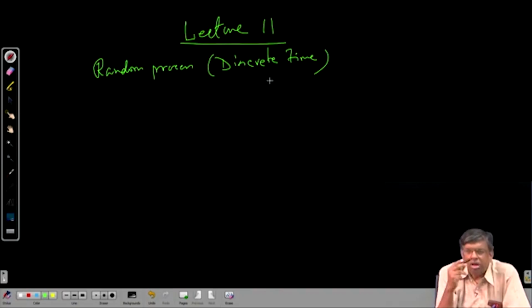So, this phenomenon of generating these random waveforms is basically termed as random process. Like if I say x of n is a random process, it means every time I observe, there will be a discrete sequence, I am talking of sequences. So, x of n is a sequence, every time I make an observation there will be one sequence x n. Every such observed sequence is called a sample function, and sample functions vary from experiment to experiment. So, x n as such is a random process and any observation of it will be a sequence which is called a particular sample function. X n as a whole will be called a random phenomenon and it is more popularly called a random process.